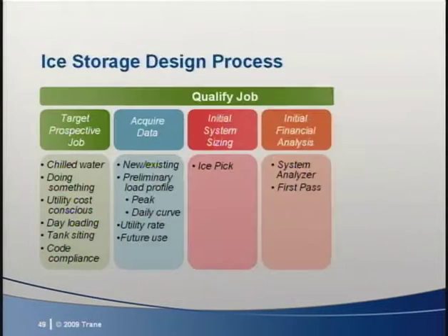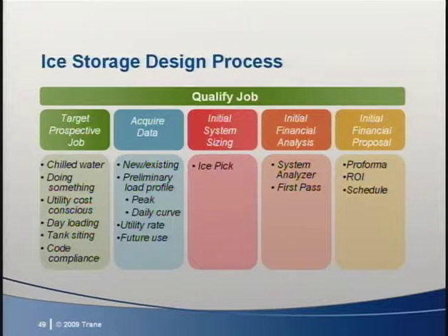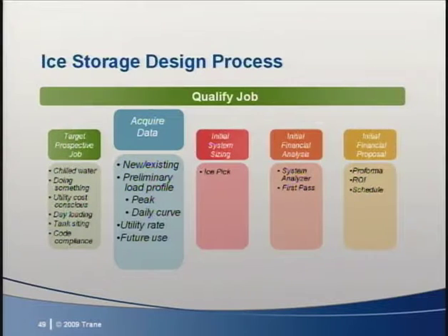The two biggest mistakes we see people making during the qualification process are failing to get a good design day load curve and assuming a blended electrical billing rate. You cannot achieve proper ice storage design and financial justification without a reasonably accurate building load curve. It has such a huge influence on the design of the system.